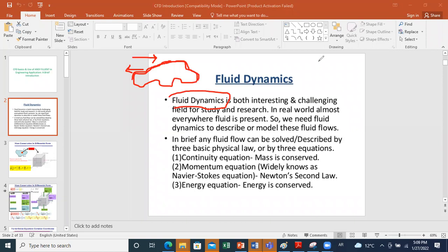You have also, whenever you have piping systems, a flow that is circulating in the system. You need to understand the characteristic of the flow, how the pressure is varying, to select the appropriate pump to use in your system, for example. Another application, even in heat transfer applications, if you have a heat exchanger, you have flows of fluid circulating in the heat exchanger. So you need to know how the Reynolds number will affect the performance of heat transfer, which will then relate two sciences, heat transfer and fluid dynamics.